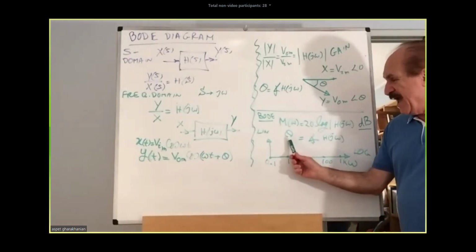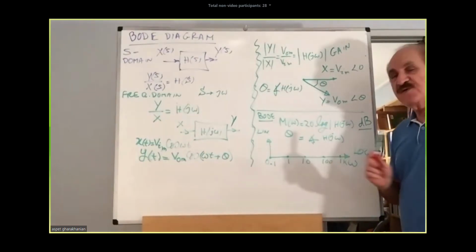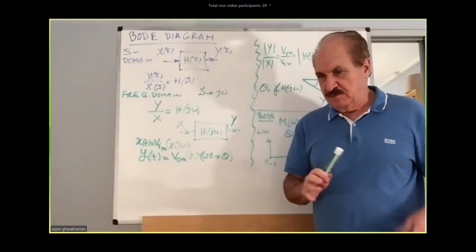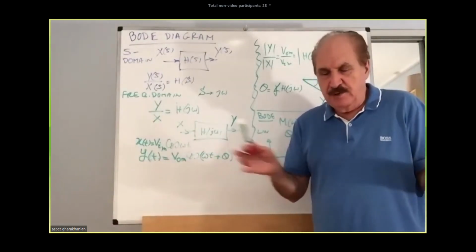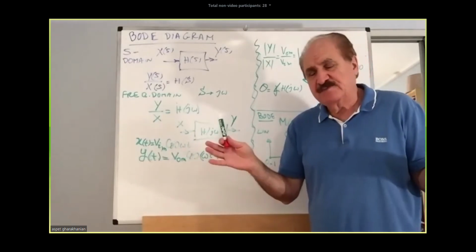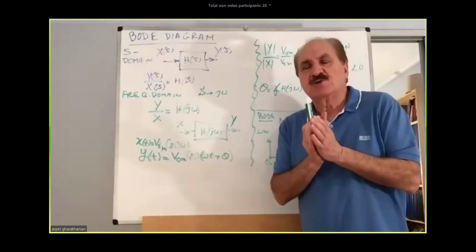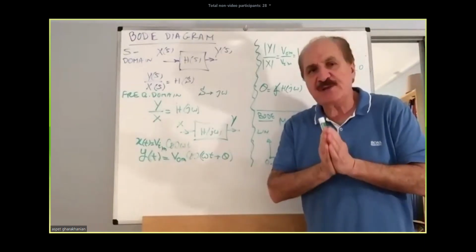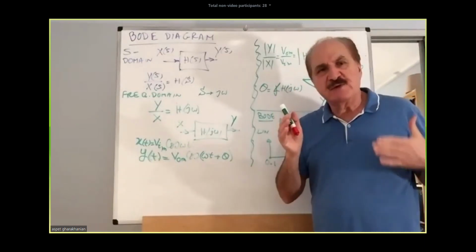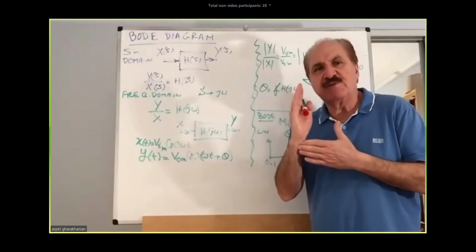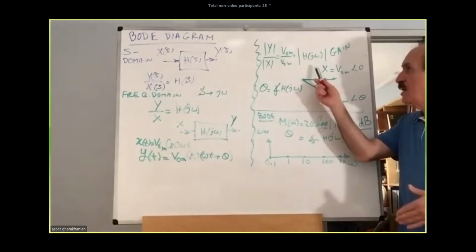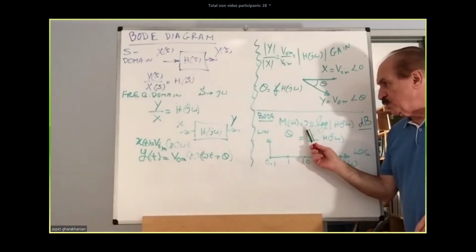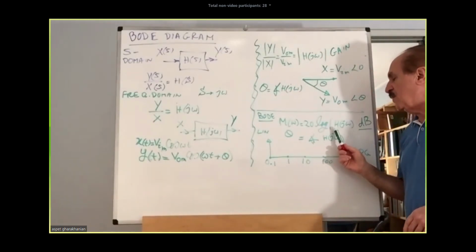However, for the angle against the frequency, we will simply choose the angle itself, linear. No logging will be necessary. So our choice in the frequency response, when we are plotting gain against the frequency, will not be the simple gain, the magnitude of H(j omega), but rather 20 times the log of the magnitude of H(j omega).